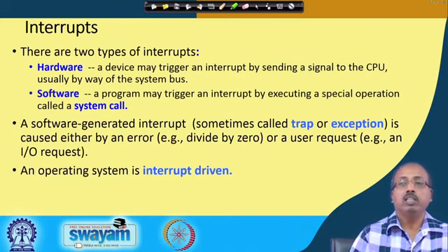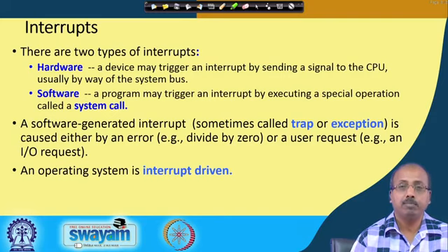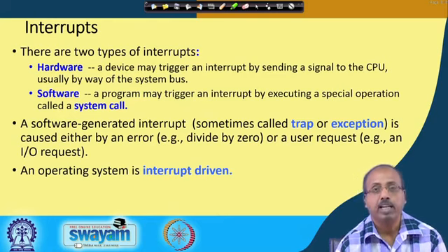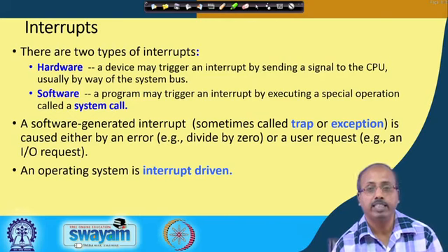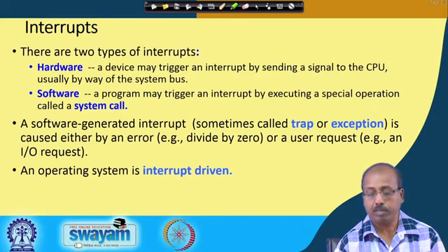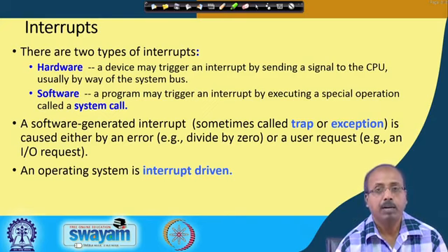The other solution is that, as and when the user presses some key, the CPU is informed that a key has been pressed and the processor takes care of that. Immediately the processor suspends whatever it was doing and comes to the operation by which it can read the content of the keyboard. This way, since the user cannot type at a very high speed, the user will not be able to generate a large number of interrupts very fast. So the overall system works very fine.